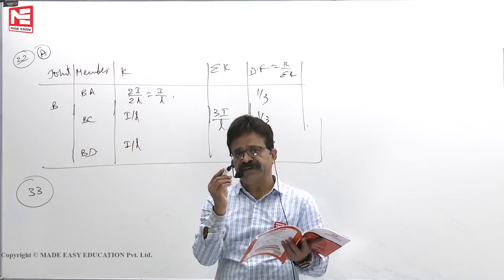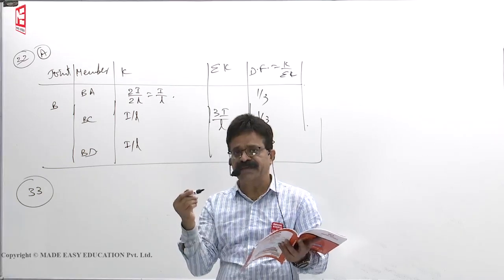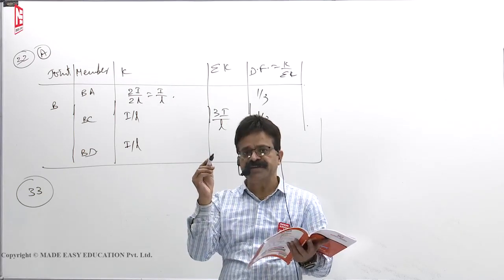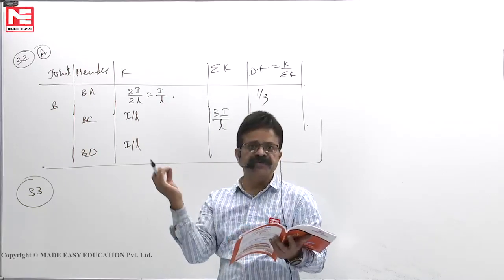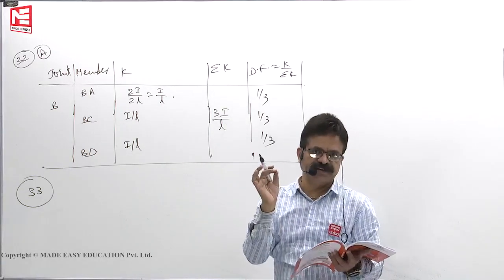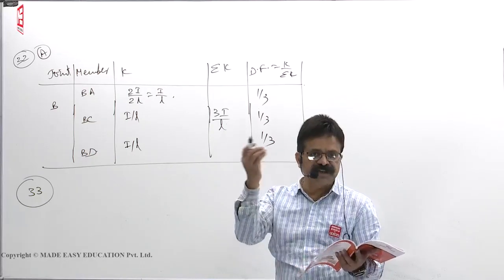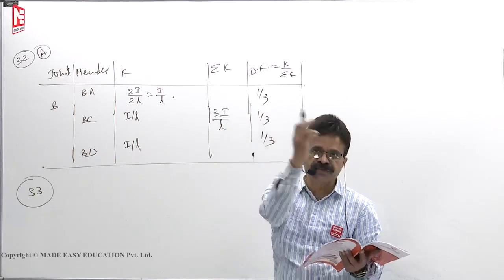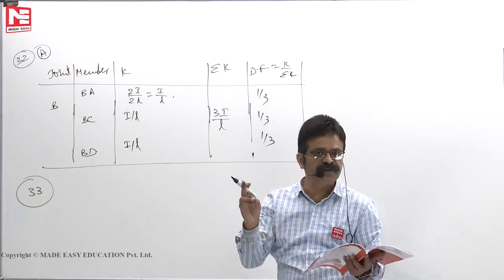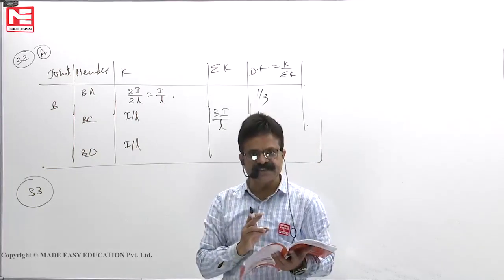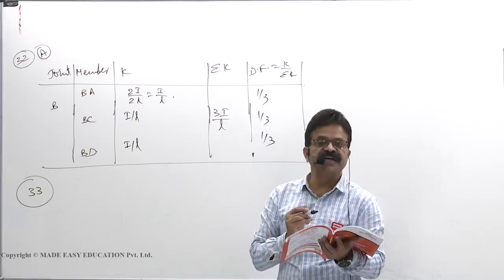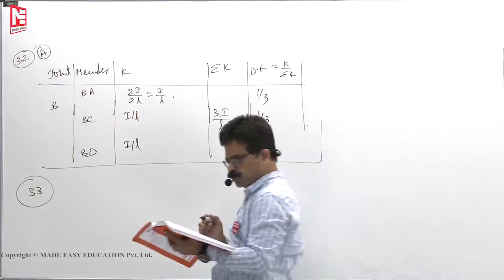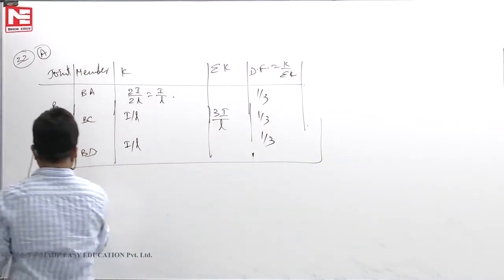So Δ, when you are writing ΣPkL by AE, actually k means ∂P by ∂W. That ∂P by ∂W we have replaced by k, which means the forces in all members due to unit load, where you want to find the displacement. So it is derived from Castigliano's theorem 2. He didn't mention that, but it is theorem 2.